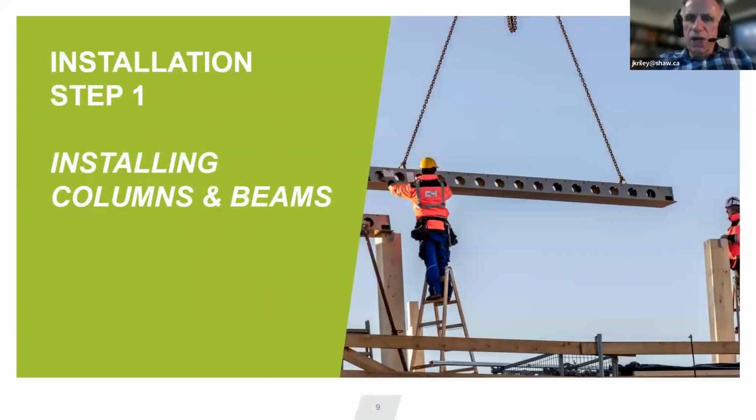So the installation of composite beams is pretty straightforward. It's always considered a gravity system. And one of the hallmarks of the gravity system here is the connections that fall over the top of the beam. So what we're doing is taking technology from big box stores and applying it to mass timber buildings in multi-level.